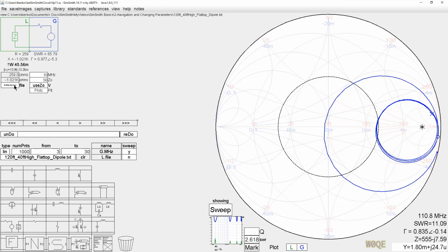If you take a regular Smith chart program that does not allow this, and you've got an impedance for your antenna, say at 14.1 megahertz, that impedance won't be the same at 14.2 megahertz. So while you may analyze the effect of a matching network, it's nice to measure the effect of the matching network with the right antennas, with the right impedance for the antenna.